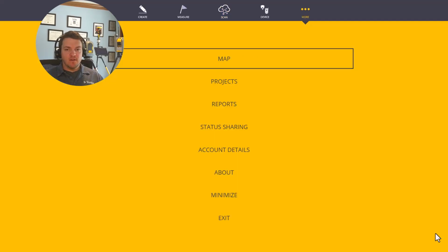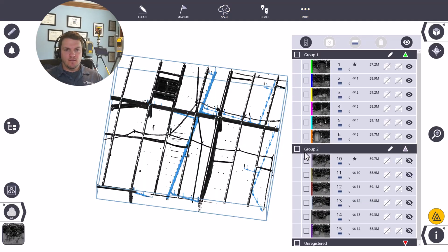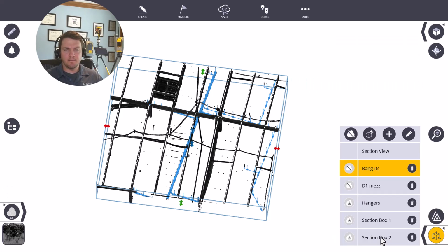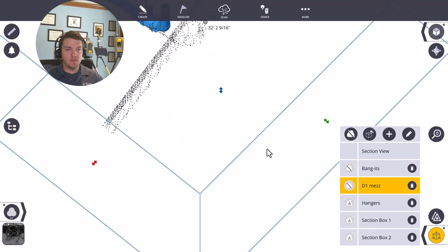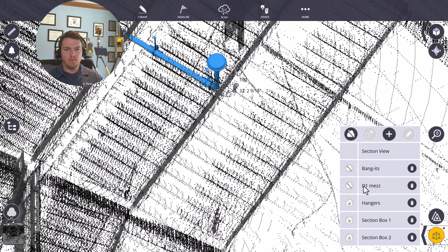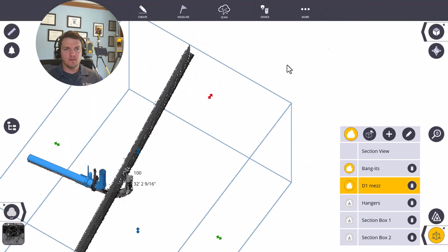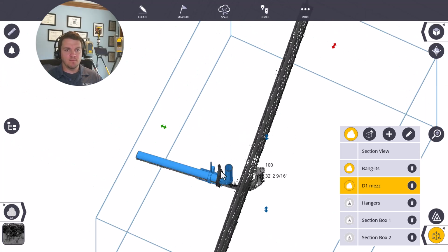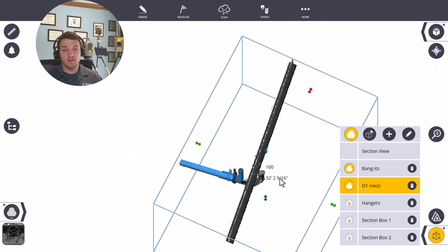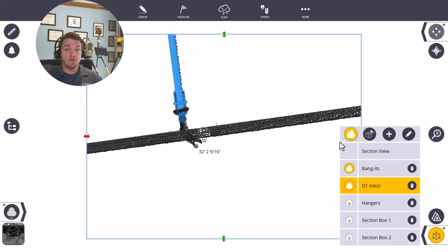The really nice thing, if I actually look at this, is if I turn on these other scan points or other scan stations, I can look at installed pipe, which will be even nicer. So here, what this is showing me is actually, hey, and what I caught, and we'll show you this here in a second, this pipe was installed on the other side of this beam. So I can denote that with a field report or even a layout point to relay that back to people who are on site. This is all on-site operations, so it's very nice.